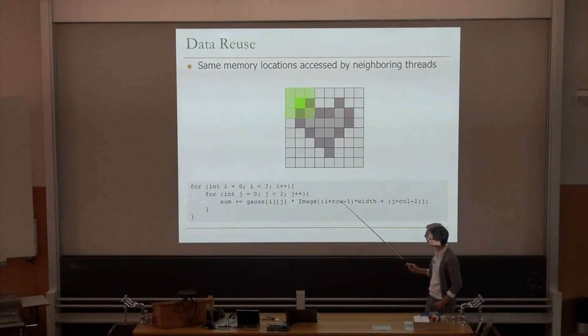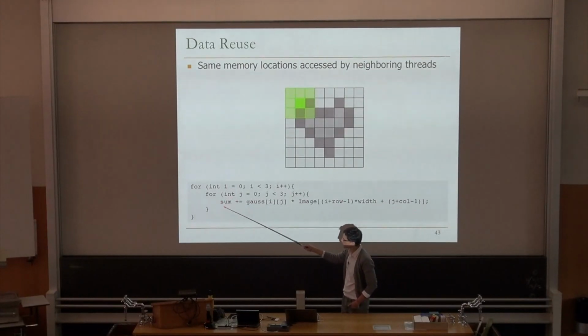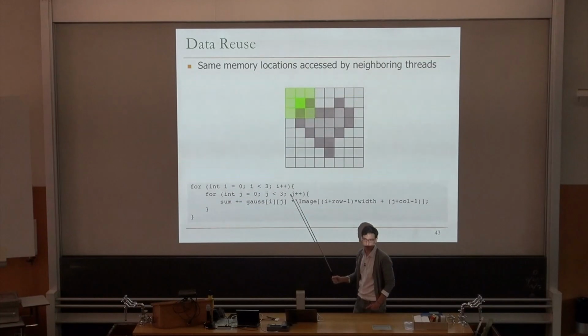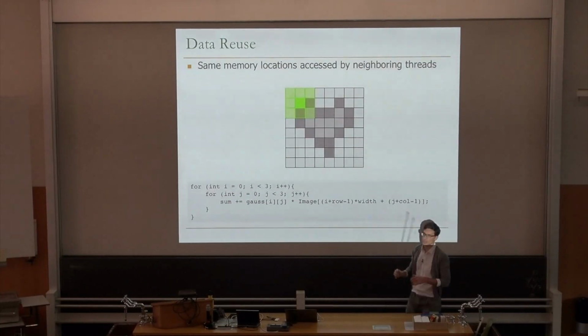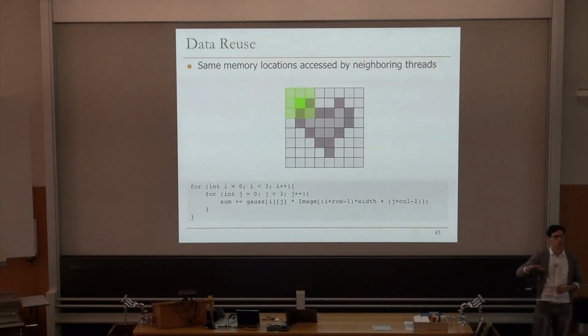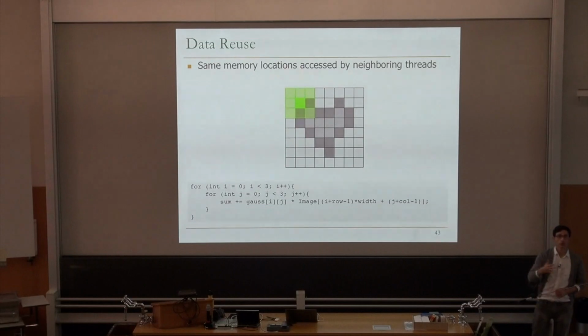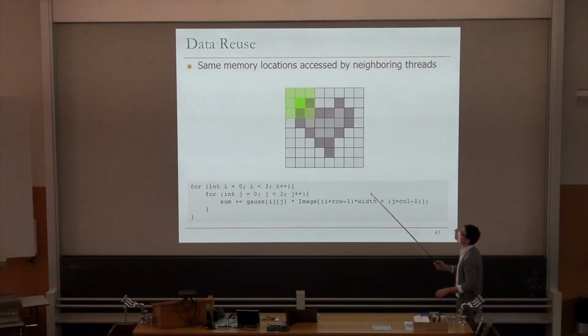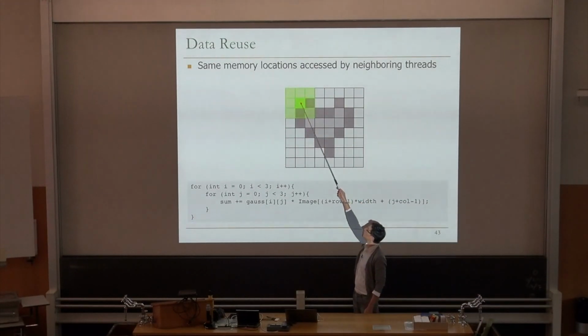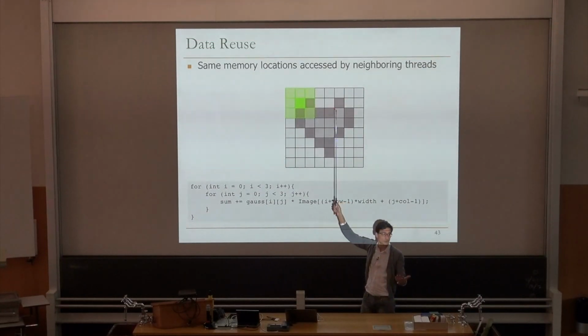And we multiply and accumulate, and the final result will be this sum. Observe that what we are doing here is some kind of equalizing the values of the image pixels if we compare the output with the input, because in the output, each of the output pixels will have something of the surrounding pixels.